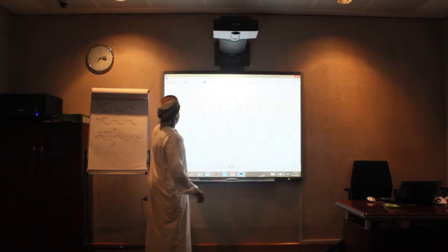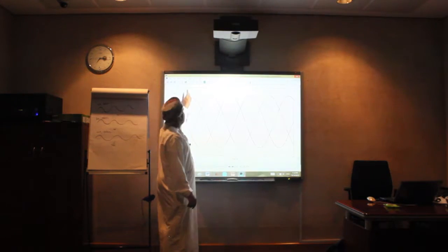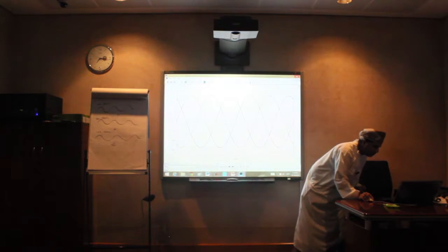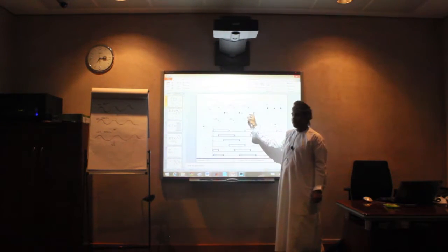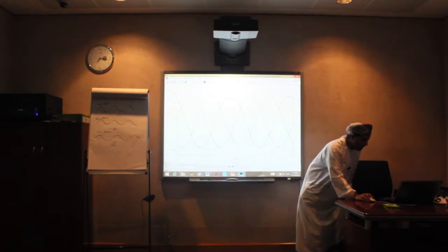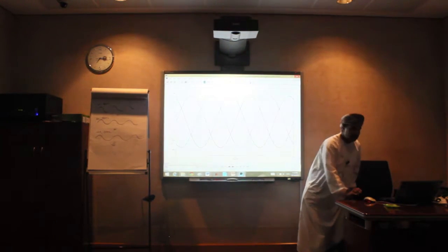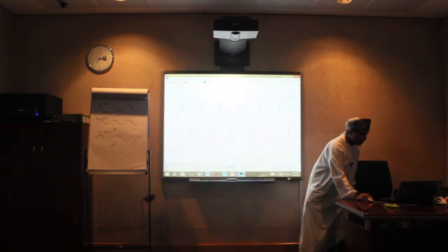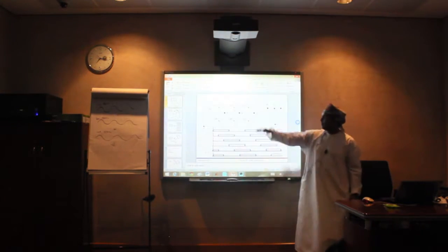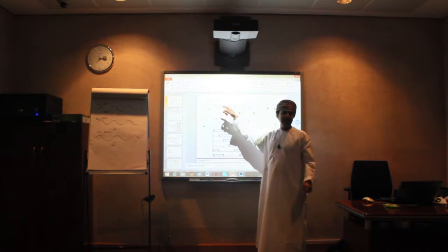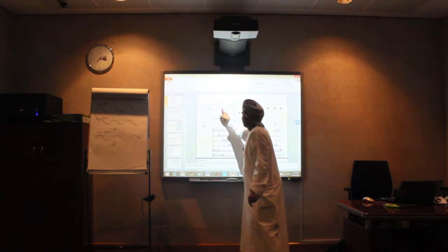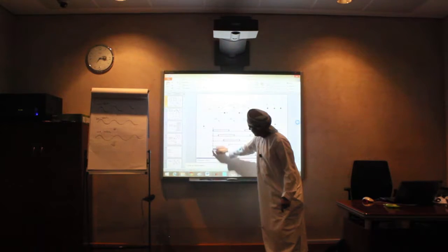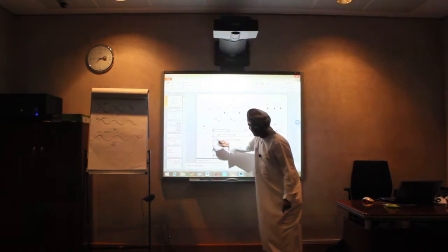If I look at that one, I will see this one is related to VC. If I'm looking at this diagram here, VC in the top is connected to which switch? 5, right? From the top. And this red one also in the top, from 0 to 60 in the positive side, right? So this red one, VA, is connected to which one from the top side? Connected to Q1. So that means from 0 to 60, I am sending two signals, one to Q1 and one to Q5. Q1 and Q5. Look at that one. From 0 to 60. Did you get it? 1 and 5.